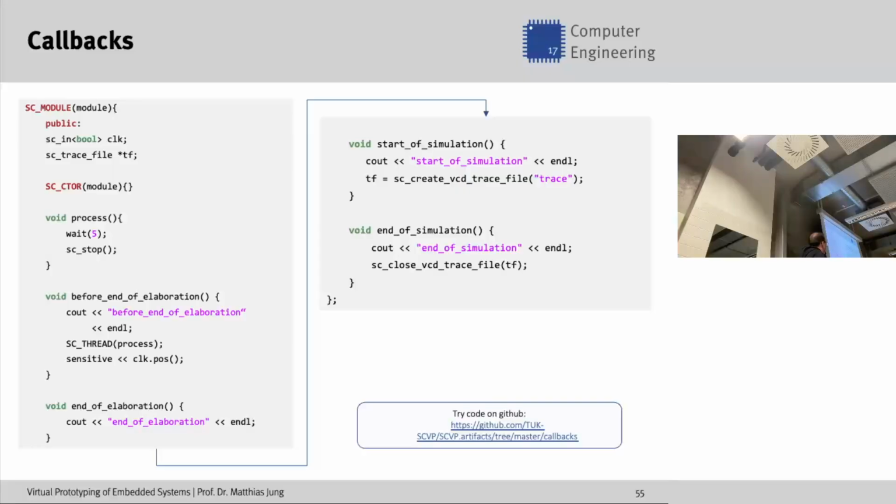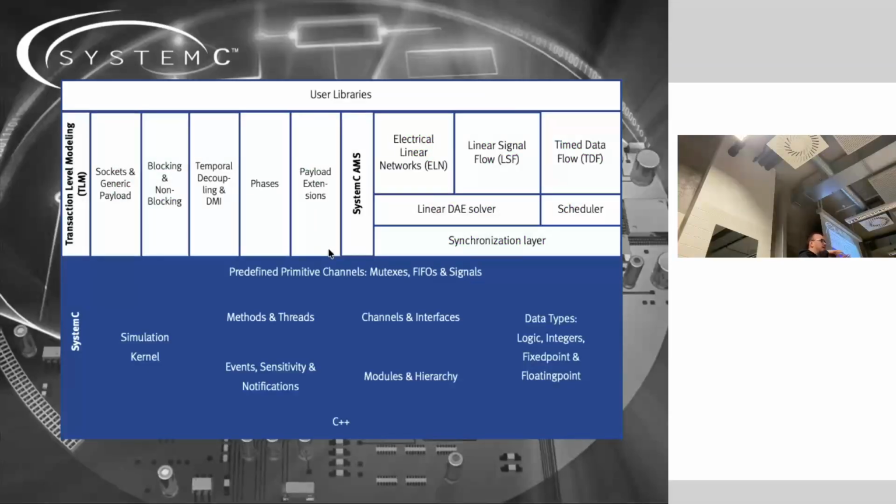Okay, so that's it with the SystemC base layer. With that we can now simulate RTL type models with signals like Verilog or VHDL. So we can now build the virtual model of a chip, one-to-one. If we know this is the RTL design, for each block that we maybe have in Verilog, we could also implement a SystemC block that does the same thing, and then we can simulate that. And usually much faster than Verilog.